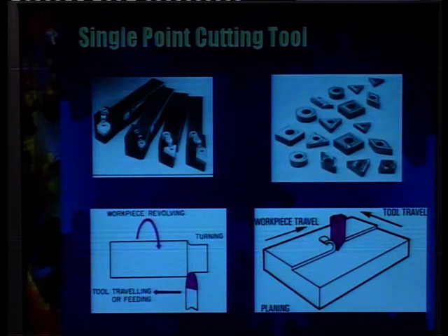steel. That particular material is cheaper, but being softer than these carbide tip tools, it requires regrinding again and again. In case we are doing some sort of professional turning, where the productivity rate, the labor cost and the machine cost are much more important, or in case we want to machine some harder material which cannot be machined using those high speed steel tools, we normally use these carbide tip tools, which are mechanically fastened onto these flanks and do their purpose.